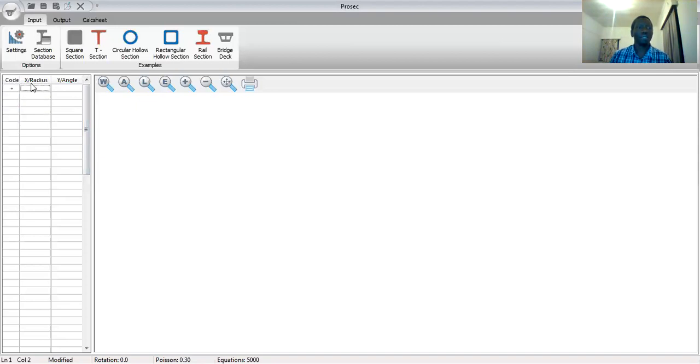And the first coordinate that I type in here is the coordinate of the starting point, okay? In my case, that's 0, which is the origin. And then I'll go to the next line. The input here is based on relative coordinates. The coordinates you're entering are based on the last point entered, okay?